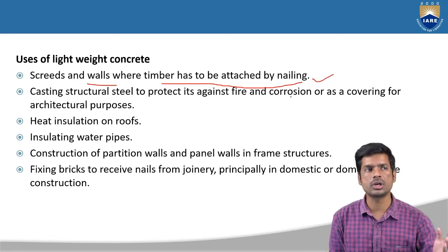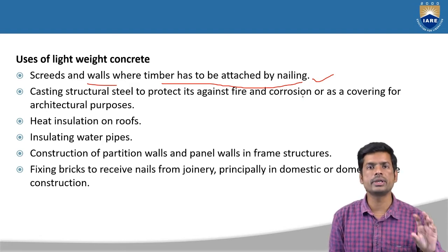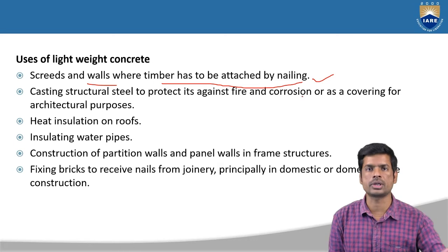If you use solid concrete, normal heavyweight concrete, then the nailing will not be done properly. We cannot nail the claddings that easily, right? So for that purpose, we are going to use lightweight concrete, so that we have some pores inside the concrete, so that they can take the nails properly.